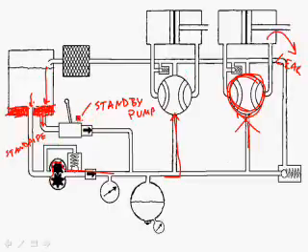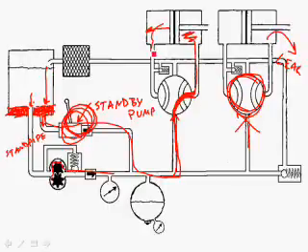The standby pump, let's say it's electric, spins around and pumps this fluid into the pressure line system. We rotate this selector valve, fluid comes into this side, and this fluid goes around to the filter and comes back into the reservoir. So it'll still work. Maybe not as well as it would have otherwise, but hopefully it'll still work.